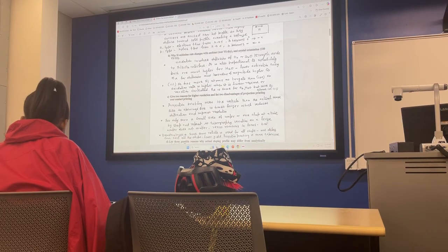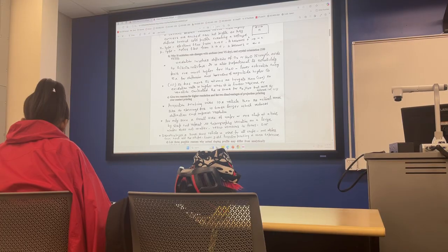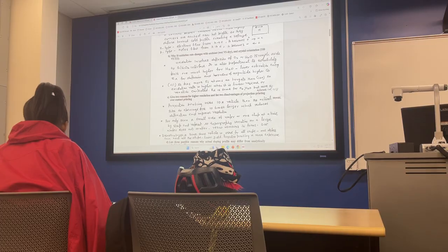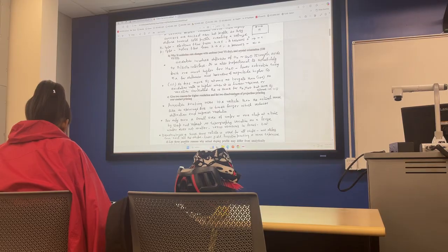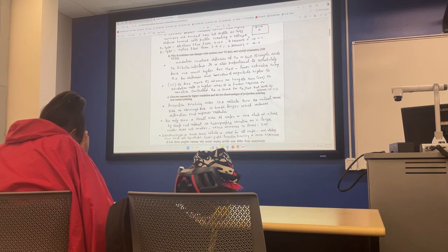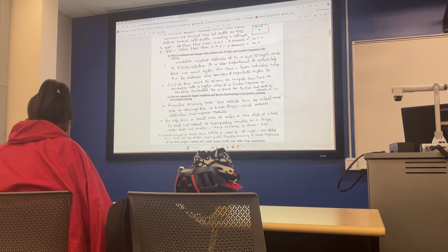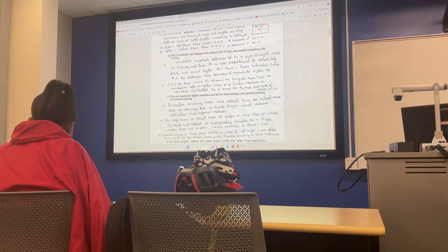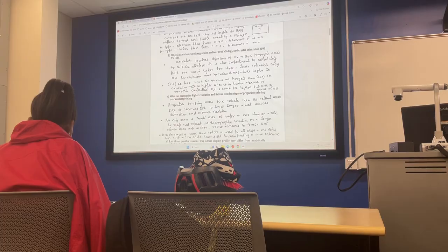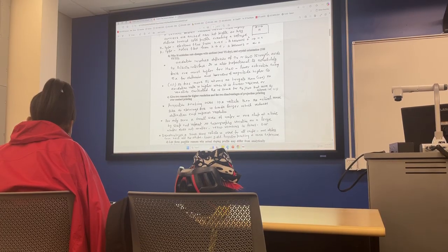Then, give two reasons for higher resolution in the case of projection printing. I was looking for two. Basically, the most important thing, which we talked about, was that in projection you use a reticle which is 10 times larger, right? So you're making a reticle 10 times larger, meaning that all the openings are 10 times larger than the actual chip size, and then you demagnify.